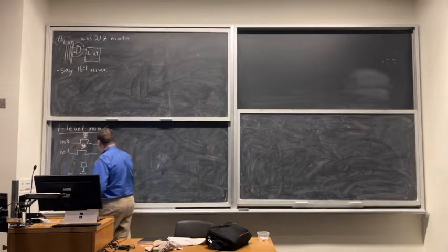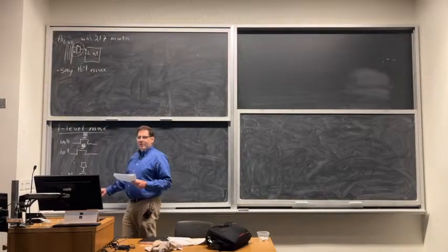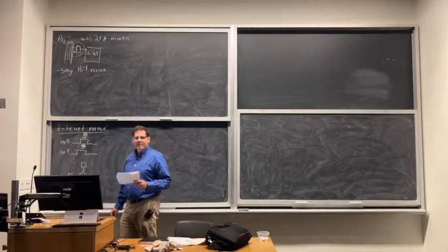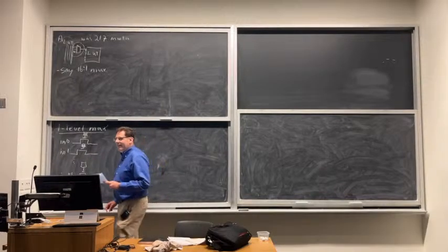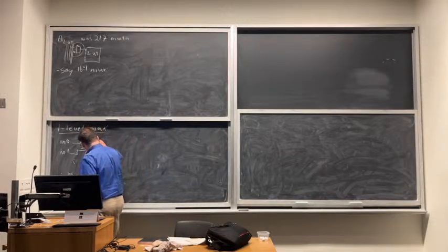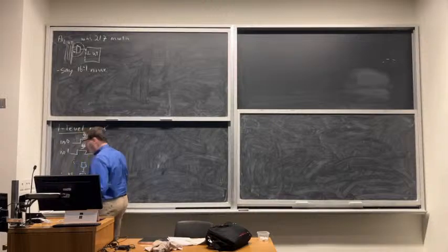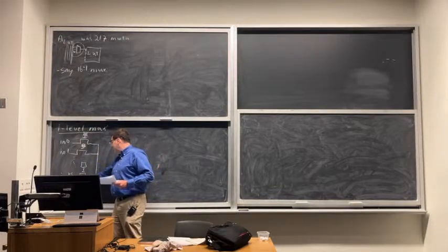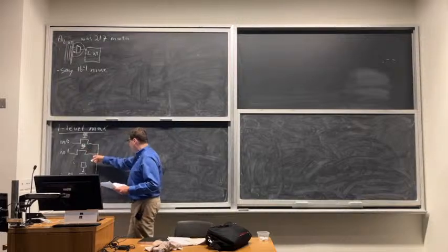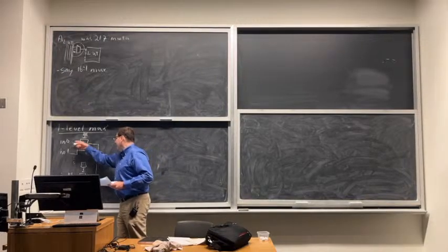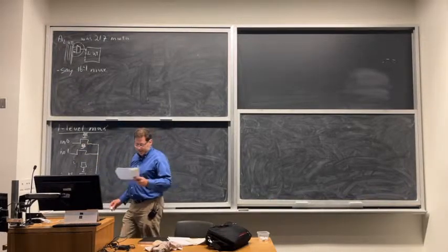Okay, so output of these pass gates, what should I do with them? What do you think? You probably know. Just stick them all together, right? They're all shorted together. So 16 inputs, program a 1 in one of these, zeros in the others. One of these values gets copied to the output, the other 15 are ignored.